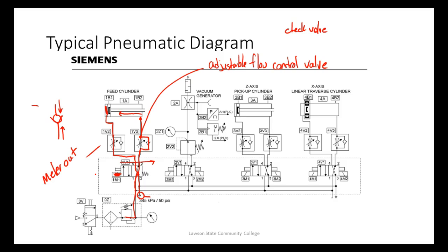So this guy is holding it, this guy is pushing, and it makes the cylinder move smooth. If we didn't do that, then the cylinder would be jerky, because as soon as it moved, the gas would uncompress, right? You understand? And then it would pressurize again. So in pneumatics, on double acting cylinders, we always meter out, which means we meter the exhaust.